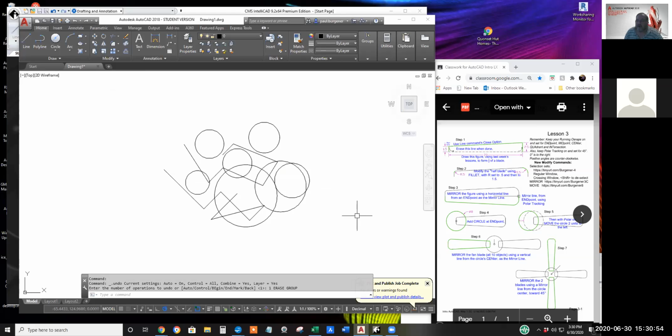Now there's a third way I want you to learn to select objects. Well, I guess you already know 3 ways. You know, individual click. You know, hit the erase and get an individual click. You know, get a regular blue continuous line window by starting on the left and ending on the right. And you know, the crossing window starting on the right and ending on the left selects everything that's enclosed or crossed.